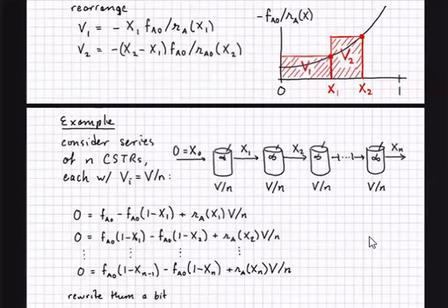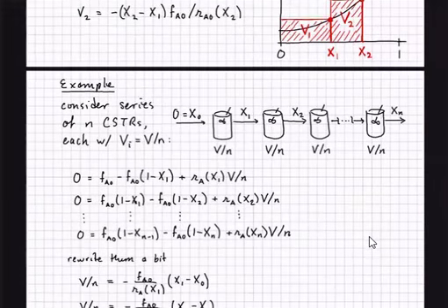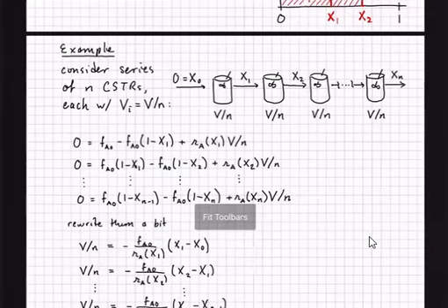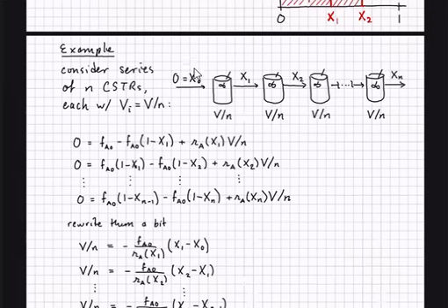and think about generalizing this idea to a long series of CSTRs in a chain. So what eventually happens to this system? Well, if I have no conversion coming into the first reactor, and this time I'm going to make all the reactors have the same volume. Okay, so I'm going to make them also add up to one volume V. So I'm going to imagine taking a giant reactor volume and carving it up into little chambers where each chamber pours into the chamber next to it. So each one now has a volume V over N, and they're in chambers.